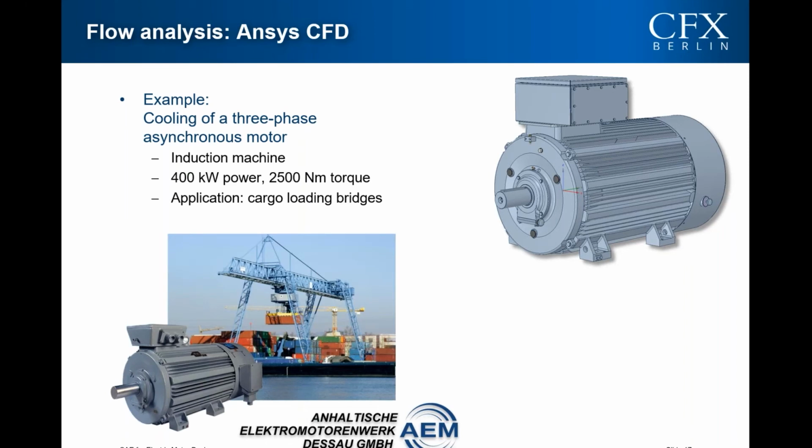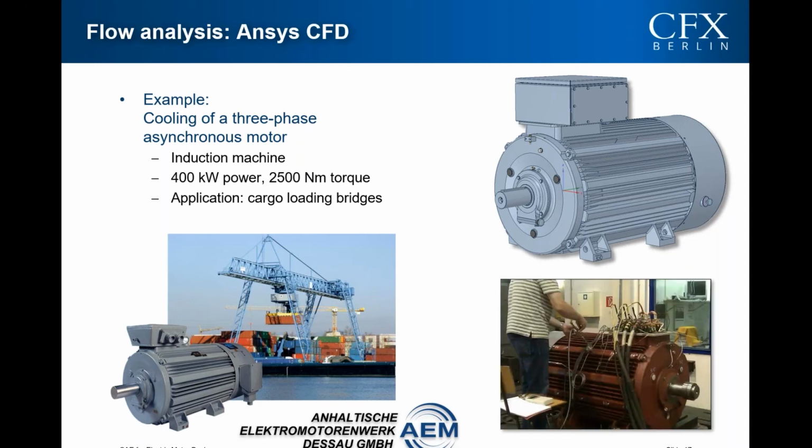With a rated power of 400 kilowatts, the main application is in cargo loading bridges. Those calculations here were done for AEM, a German manufacturer of electric motors and generators. The aim was to benchmark the accuracy of the CFD calculations, and therefore the results were validated with measurements of temperatures and flow velocities.